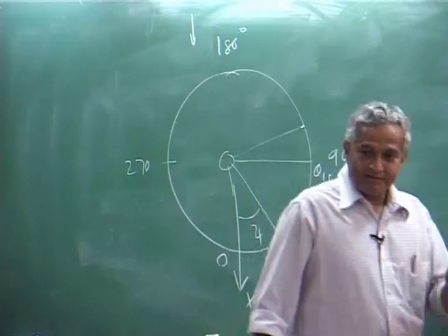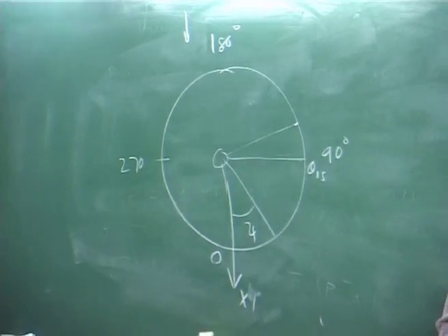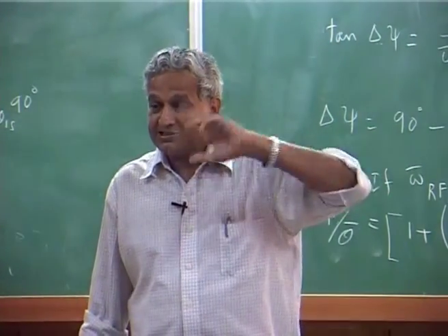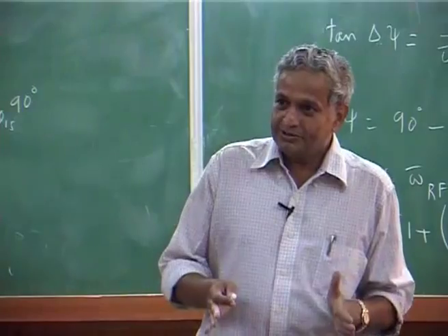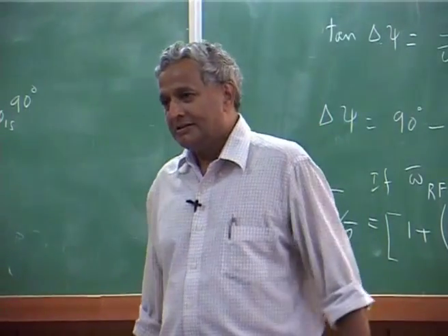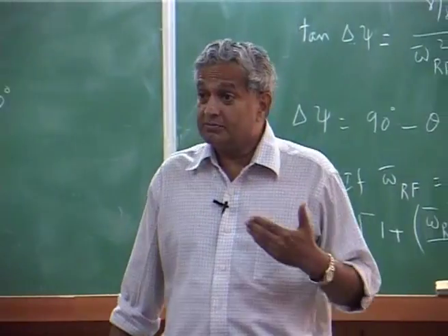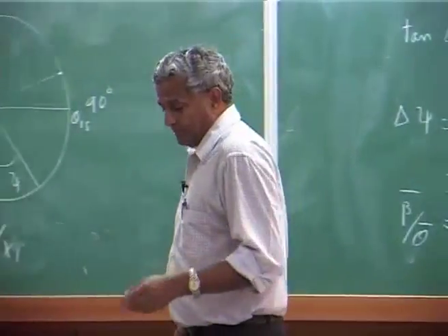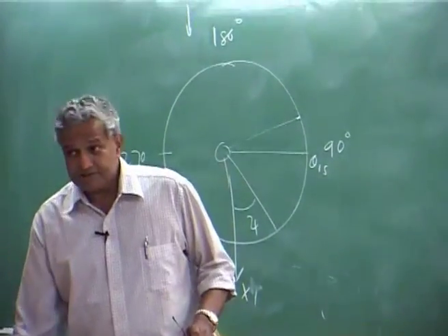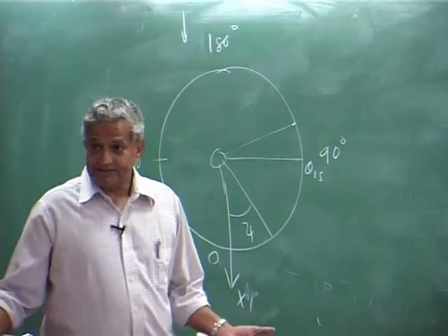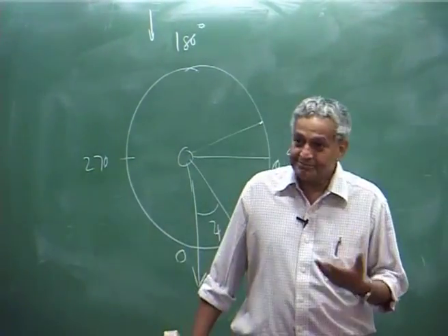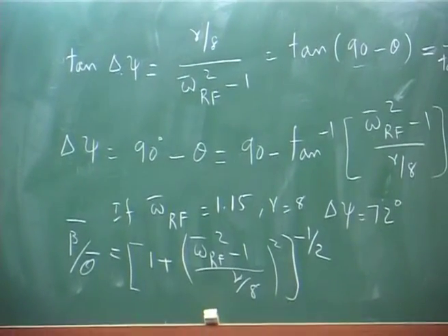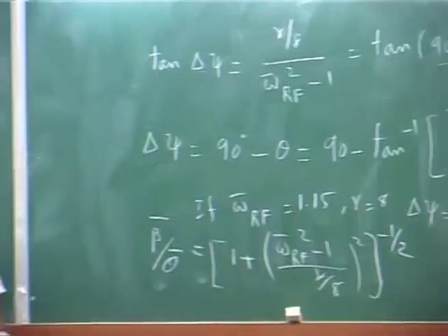Now, you imagine that the design, the layout depends on what your flap frequency is. So, everything is linked, even your design, your layout, many of these things are linked to flap. Otherwise, you are actually increasing the load of the pilot, because he still has to do a lot of control. Now, this phase angle, is it constant? That 72 degrees, whatever we got for this, is it fixed? No, it may vary with forward speed.